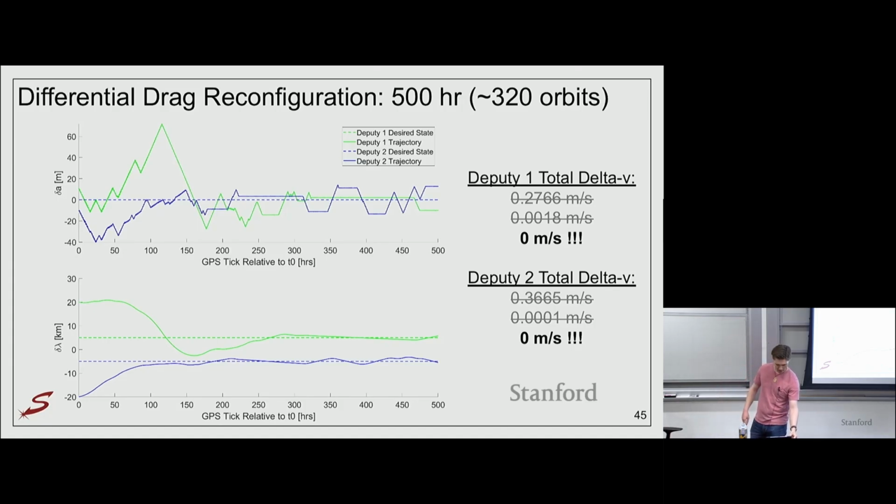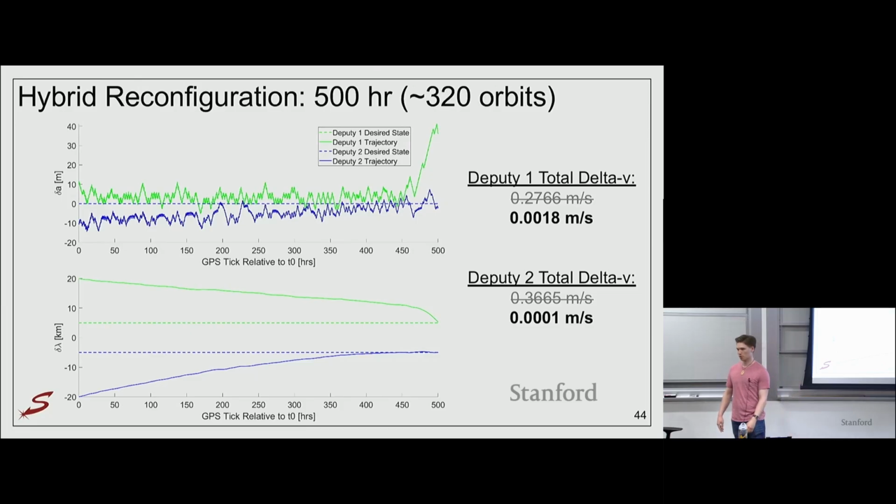So in this sense, I've told SwarmX to use hybrid control, so it's going to use both differential drag and propulsive control. And actually, part of the reason why this system is convergent is that it's only resolving the differential drag maneuver plan. The original propulsive plan that it starts with, it does not change, because if you change it, propulsion starts wanting to take in the errors and add cost to fix those errors, and we don't want that. So we're actually accomplishing this error rejection using differential drag modulation alone. I think that answers it.